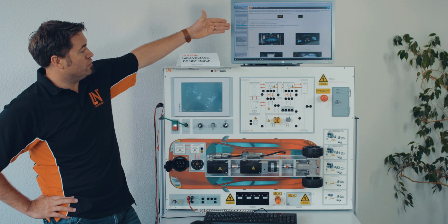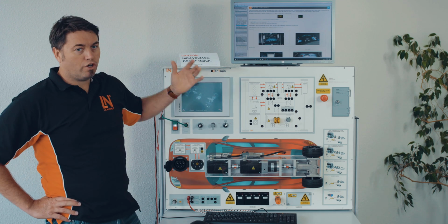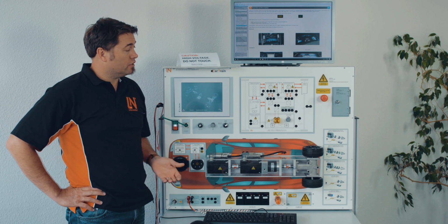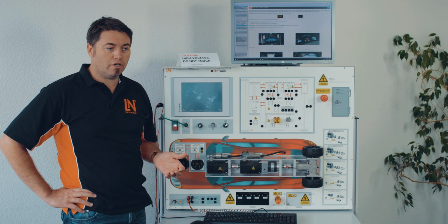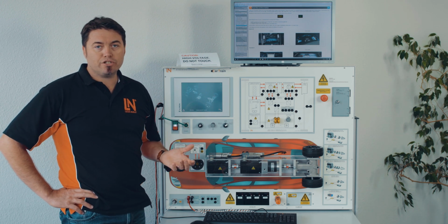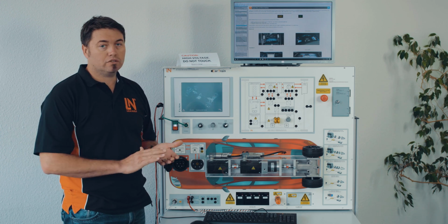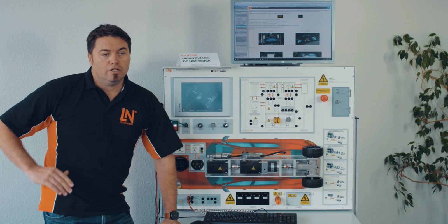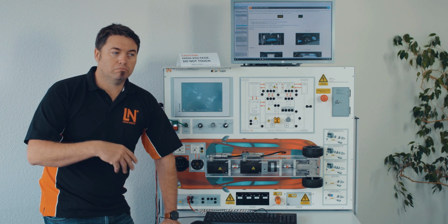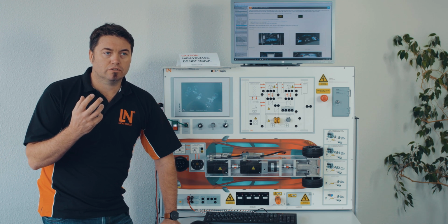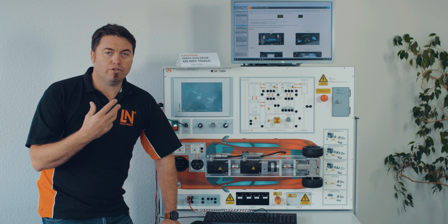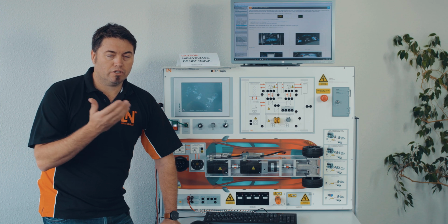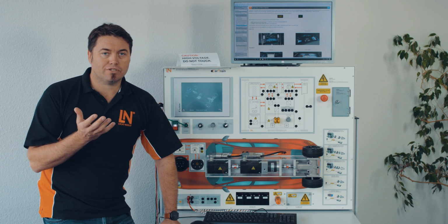When the vehicle is ready, of course you need to be aware. Very important when you're servicing: the combustion engine can start straight away when the battery level is low. That's happened many times in the workshop where the technician has driven the vehicle in, because the engine is not running, they've parked the car, and then all of a sudden the combustion engine starts when they're not ready.